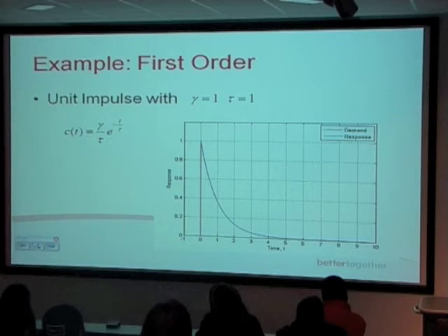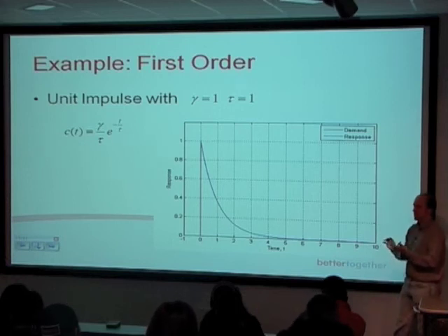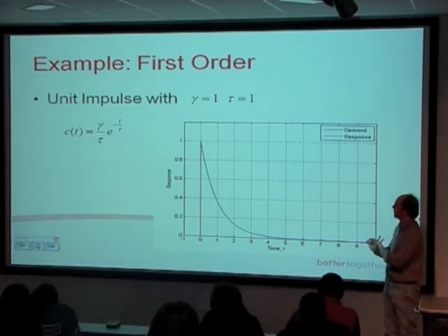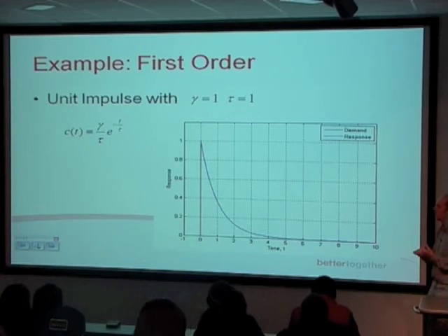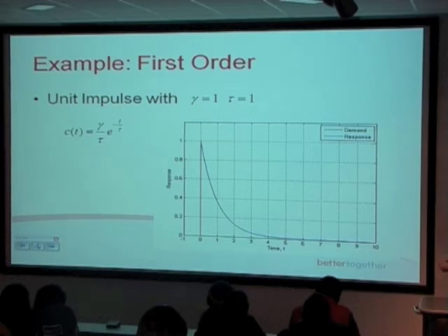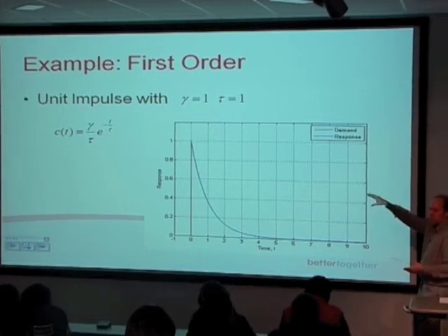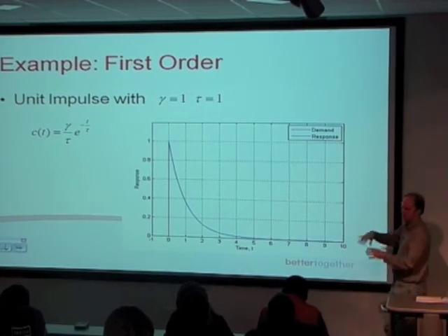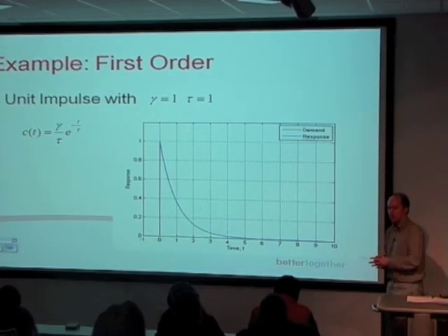Okay, so what we've done so far is we've gone through the different types of inputs. Okay, a step input, a ramp input, and an impulse. And what we've then done is we've looked at a standard first order system. Okay, we've rearranged it, we've applied the input, and then we've gone back to the time domain to plot the response. And often going back to the time domain will involve partial fraction expansion. Okay, which is simple sort of GCSE level algebra, but you've got to do it. And then you look up on the tables to find out what the time response will be for those standard forms. And like I said, you can often use the table as a hint to find out what you need to convert it back to.